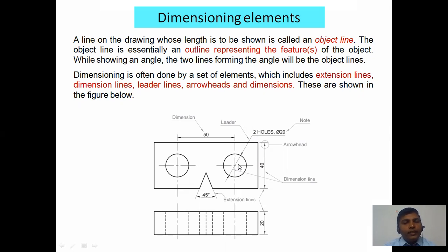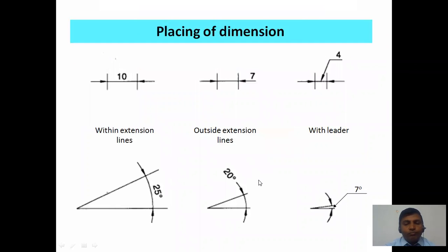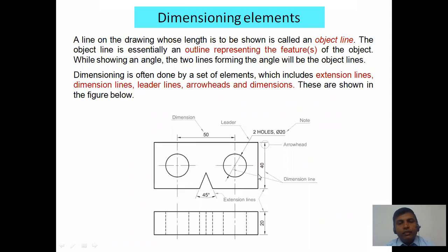And the 5 indicates the diameter of this circle. Again, this 40 indicates the size of the dimension. That is the size dimension. Okay. Then the angular dimension, the angle between the notch. Such kinds of features you have to use in the actual drawing, and this is most important to show the dimension, to show the features on the diagram.